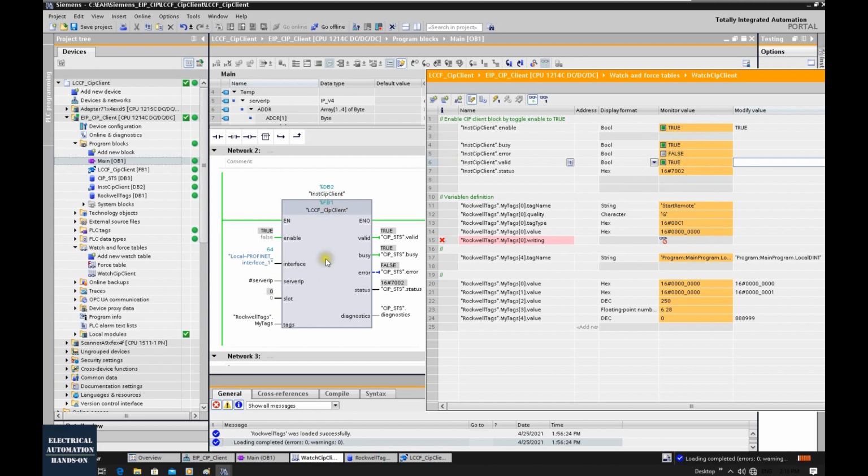But that means for this current version of this function block, we have to restart this controller, or cycle power the controller. That's not quite good. Hopefully in the next version, Siemens can give us a reset way, basically restart the sequence inside and allow this system to reconnect the correct connection.